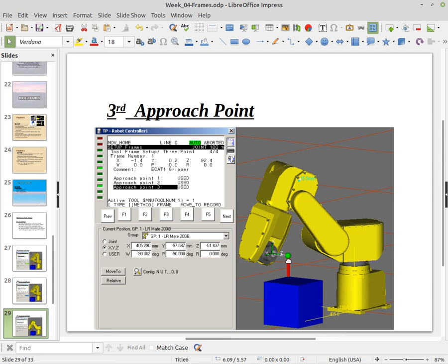And again, when you do this, you have to make sure that the robot can get to it. Sometimes, like this one's going down on the right side, based on the robot's reference, or on our reference, it looks like it's on the left of that point. But a lot of times we may not be able to reach that, so maybe we have to come down at the right, and it doesn't have to be perfectly left or right.